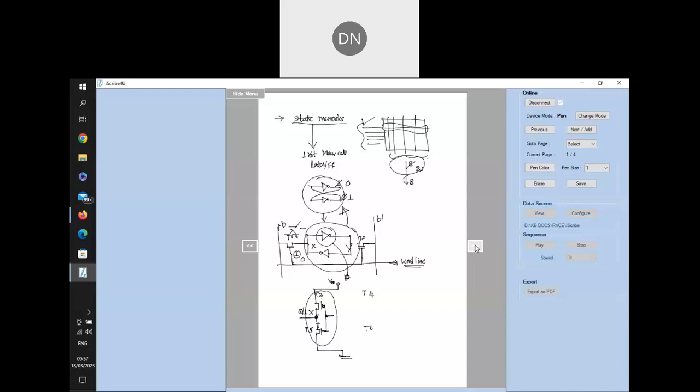So now we will write another inverter. One more inverter, I'll be writing it. Again, I'll be putting it in the opposite configuration. So T6, I will write this as another transistor. Both of them I'll short together, and it becomes the Y. The output of this I connect to here, and the source I'll be connecting to the ground. So again this is a common point.